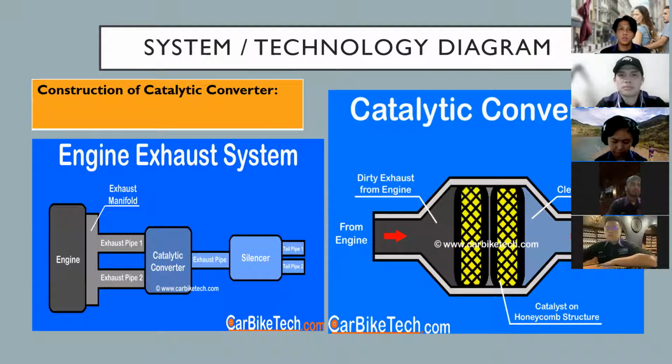At first, it reacts with the carbon monoxide generated by the combustion of gasoline. It also reacts with the hydrocarbons formed by unburned fuel and other nitrogen oxide emissions. Thus, the catalytic converter converts this gas into less harmful byproducts, which are carbon dioxide, water vapor, and nitrous emissions.